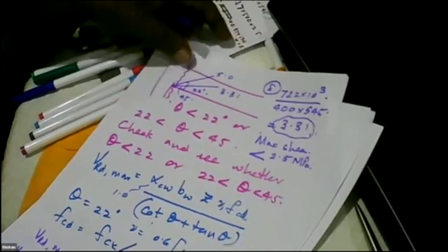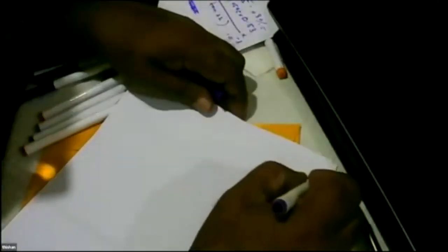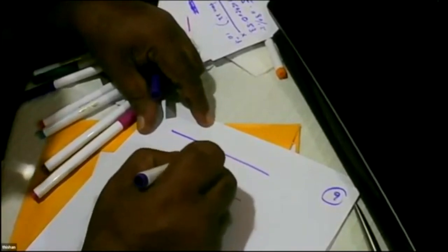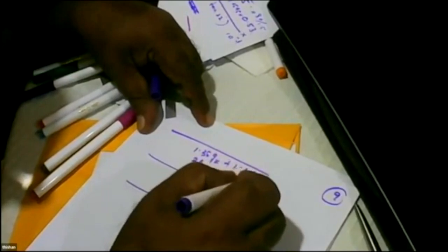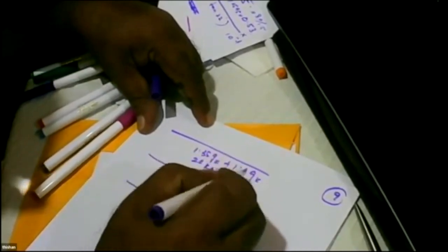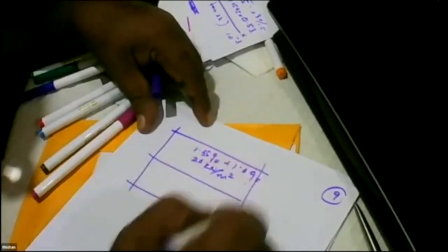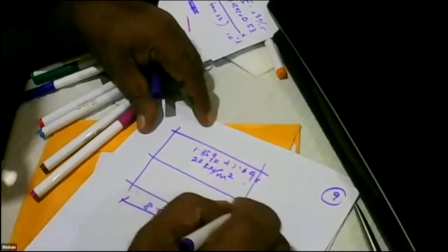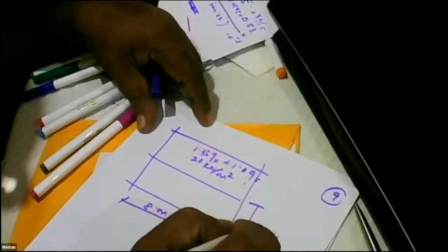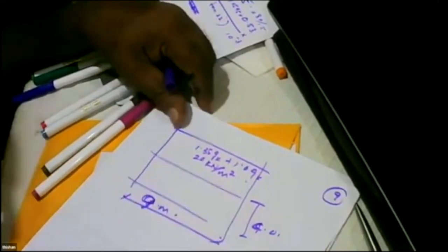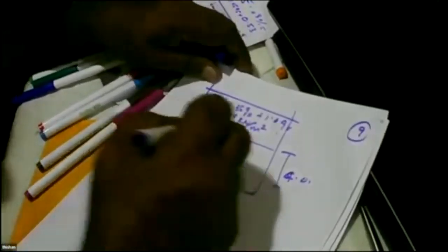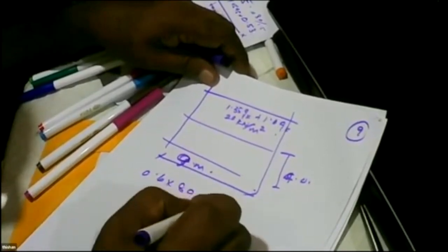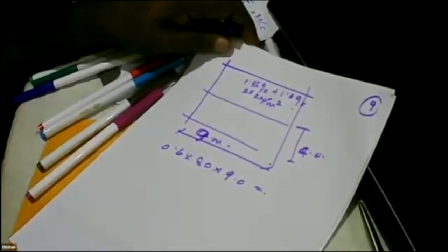So when I'm selecting the general arrangement drawing, how could I do that? Okay, I have a building, heavily loaded. Say 1.35 GK plus 1.6 QK is around 20, a warehouse. And these beams are one way, 8 meters long, and these are about 4 meters. These are 9 meter spans, heavily loaded. 20 into 4, 80. 80 into 9, times 0.6. What is the value? Big shear.